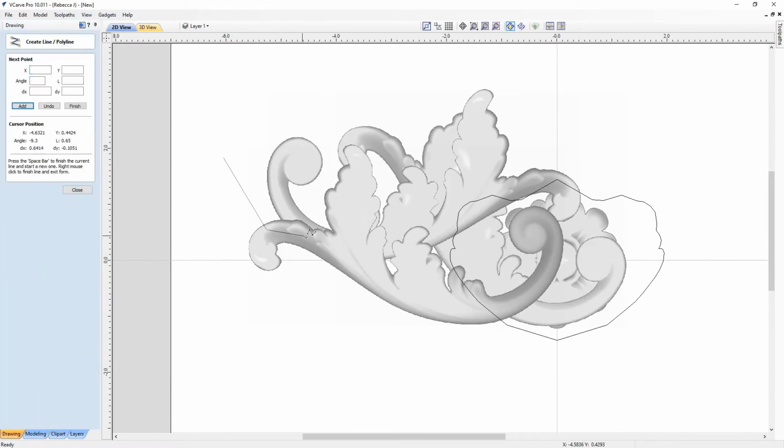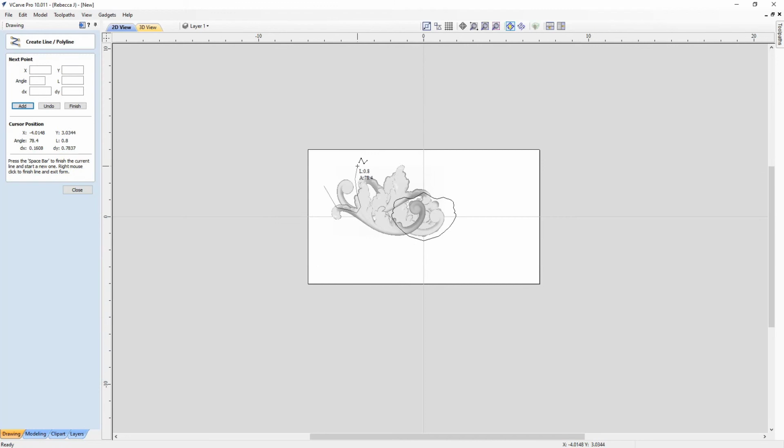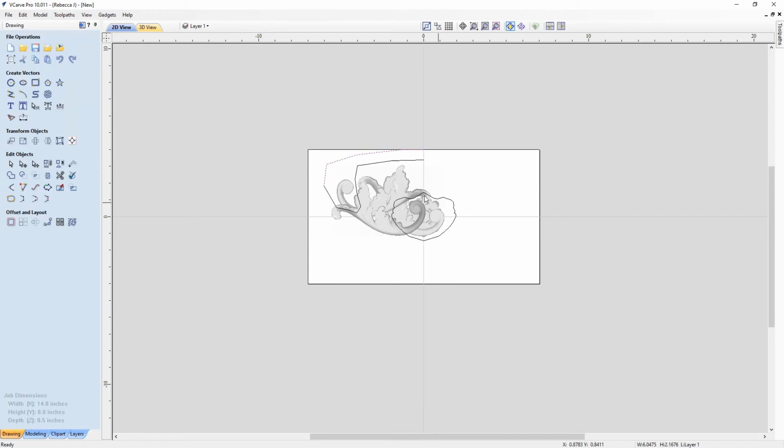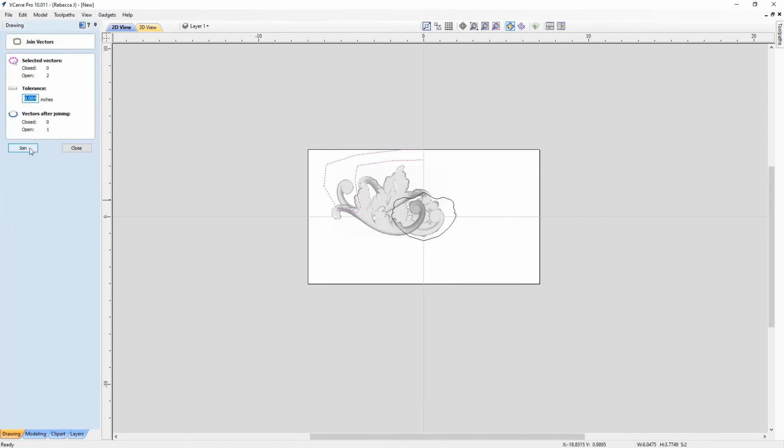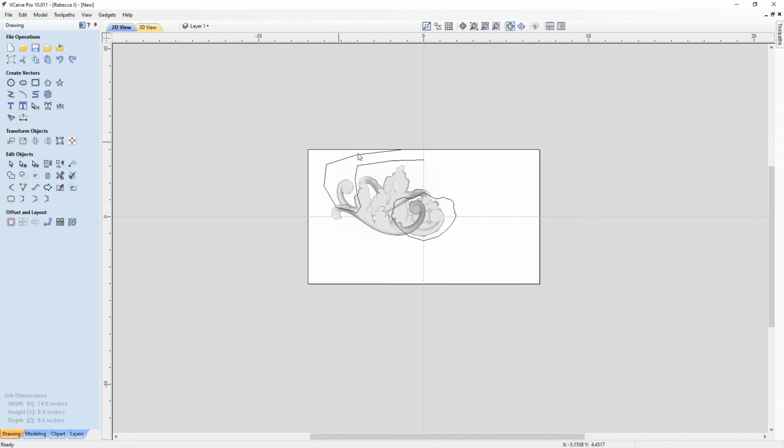So this one needn't be very carefully drawn. And then again, as always, as we are using the mirror tool, we must make sure that we line that up to the center, and we'll just bring that over as well, like so. We're going to shift and select those, and we're going to join them. So we're going to join like so, and then what we're going to do is Control, Shift and H to flip that horizontally.